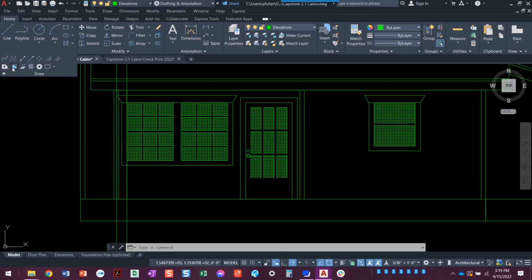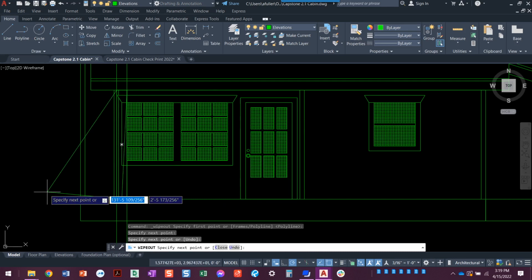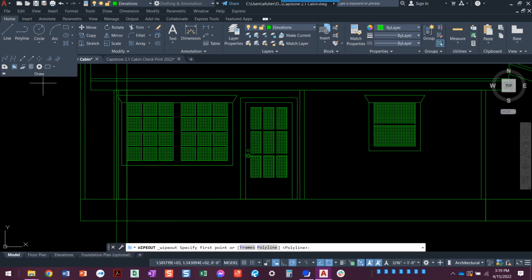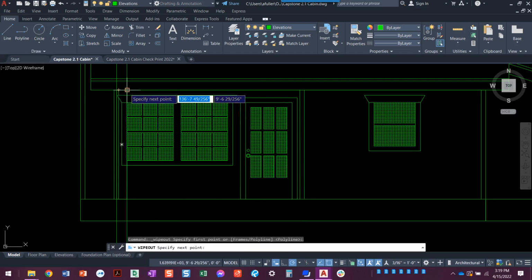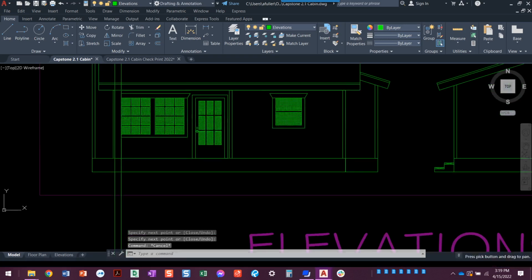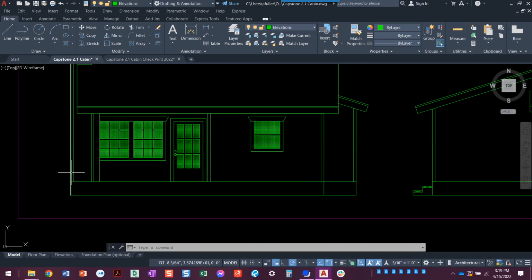So we're going to do the wipeout command again. Remember the wipeout command? We did it earlier on this same window. Oops. Let me get rid of that. Wipe out. I accidentally snapped in the wrong place. There you go. To here. And then when I press enter, see how it just kind of hides that window behind it? Get rid of those construction lines. Now I've got the front post here and the window behind it is hidden. So again, I'm a huge fan of that wipeout command.